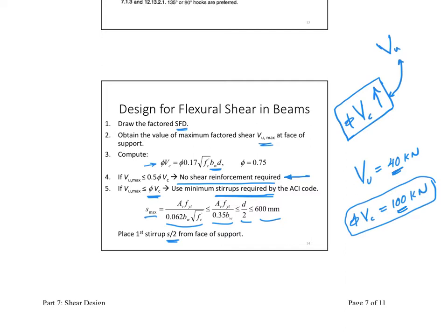If you're going to use stirrups, you're just going to use them for detailing purposes to hold your cage in place. Now imagine the second scenario. I have an applied shear equal to 80 kilonewtons. Well, I have the same section, so it's 100. Now my 100 is more than the applied shear.